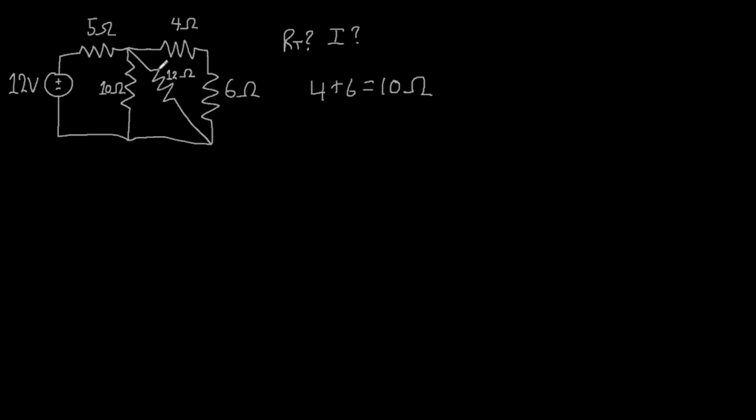Then take a closer look. Remember what I said about the positive and negative ends? The positive ends are here for these three resistors, and the negative end for this resistor is here. And see what they all have in common? The negative end meets on this wire. So therefore there are three resistors in parallel. And calling on from the previous solution, I would use this formula to sum up the parallel resistors, which gives you an answer of 3.53 ohms.